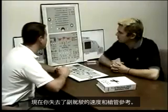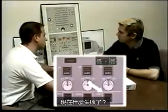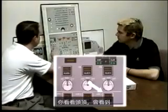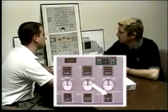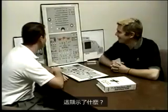Now you lose the first officer's speed and baro reference. What's failed now? ADR 2. You look at the overhead, you see a steady fault line on ADR number 2. Yep, I see that. That's an indication of what?